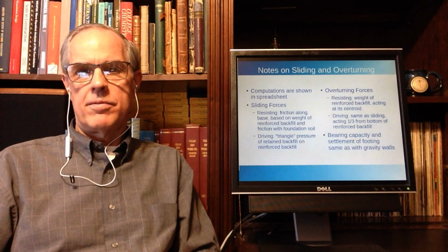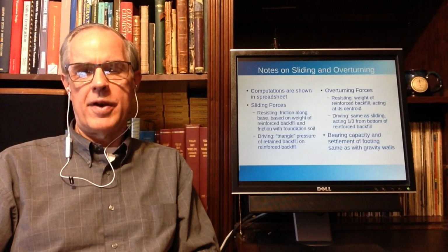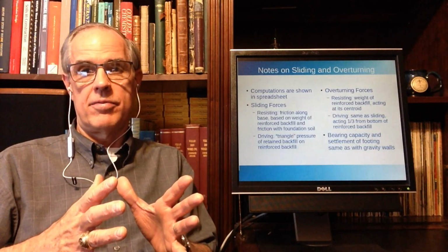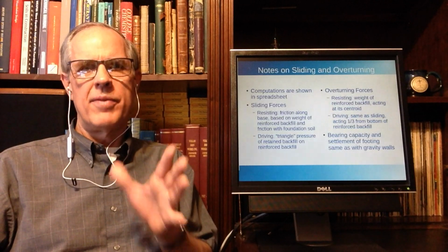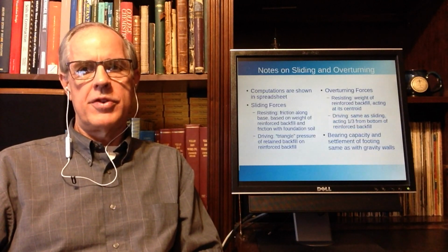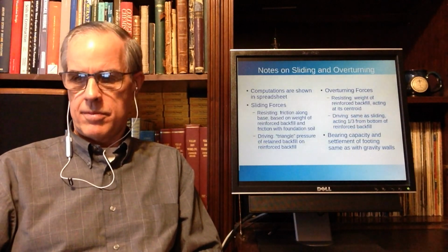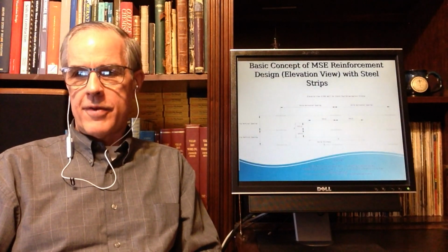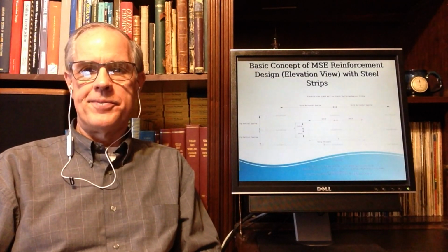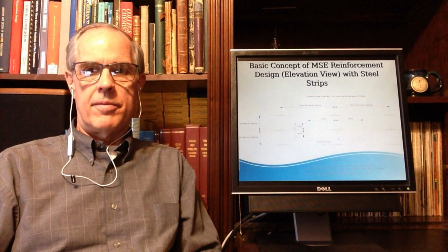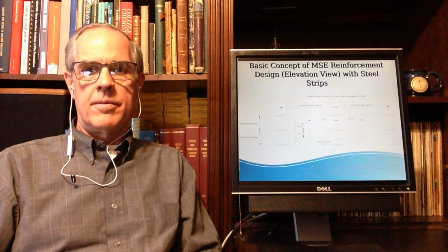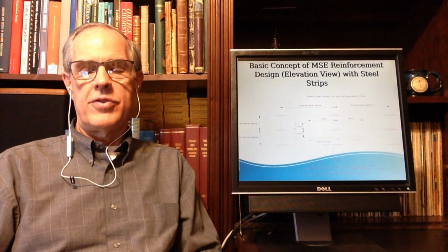Most of the time, if you get a wide enough retaining wall, your problems will not be with bearing capacity at the footing. For the whole wall, most of the time that'll be a settlement issue. This is a diagram I face, and I know it's hard to read, but in any event, it's in your slides.